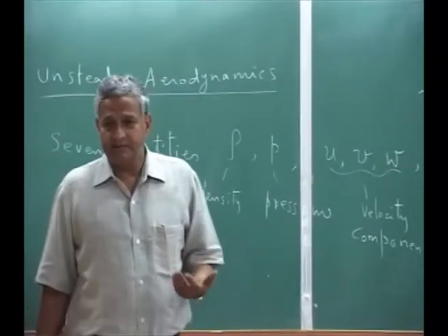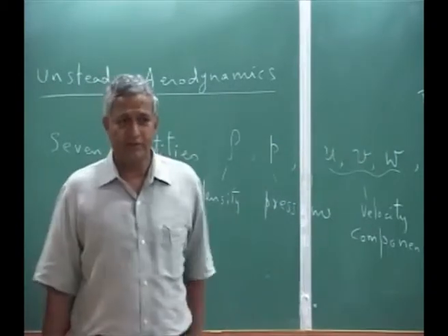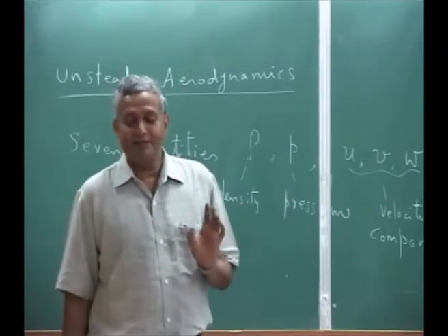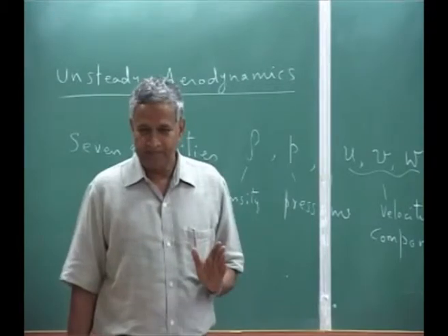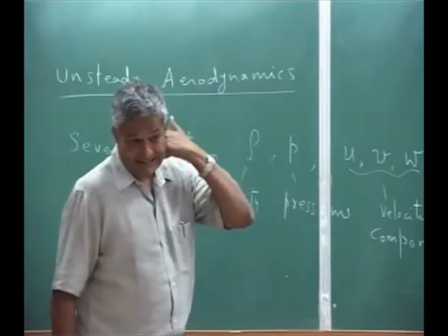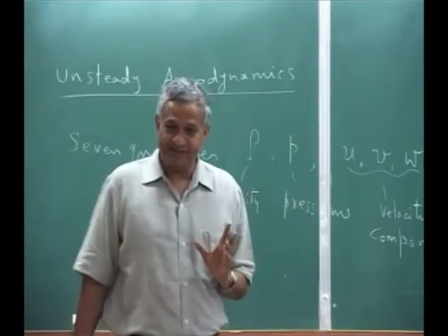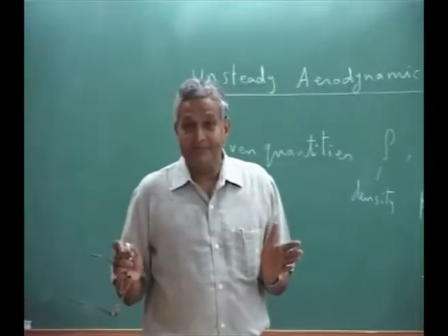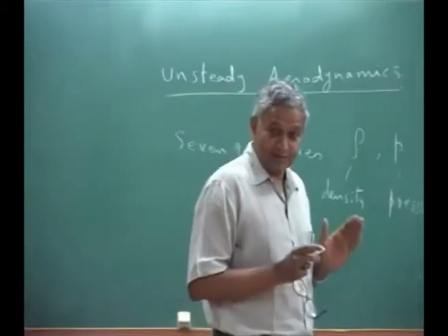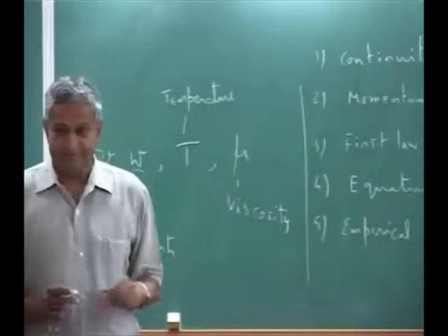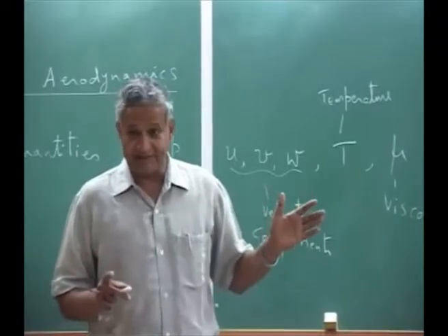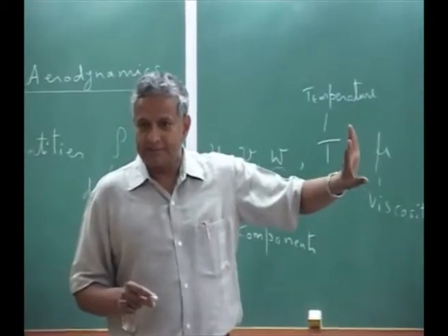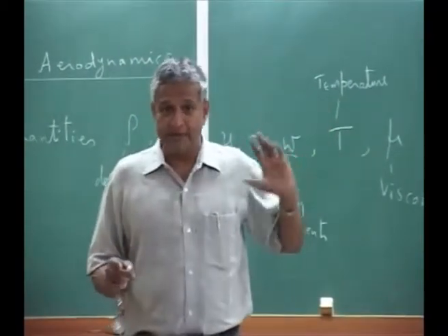But then the applicability of whatever the potential flow, it is fairly good for most of the flows, except that when you have a very strong shock where there is a heating happens, then these equations are not valid. This solution is not valid. But still, people use potential flow for transonic also. Please understand, the industrial codes are based on that, okay, for aeroelastic analysis. It's not that they do Navier-Stokes work. People are developing it. That is a different matter. But it is still a field of research completely.